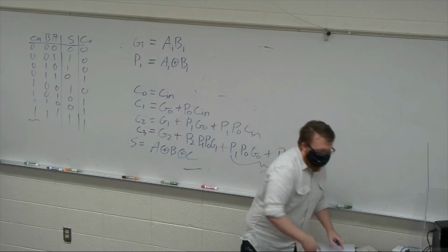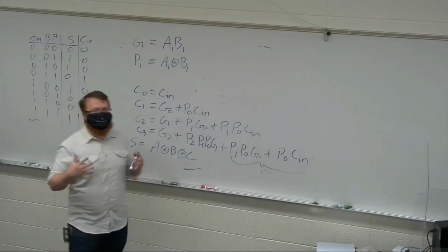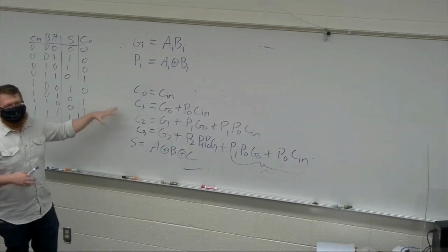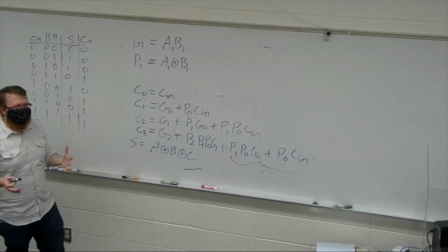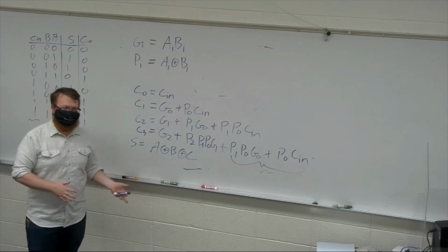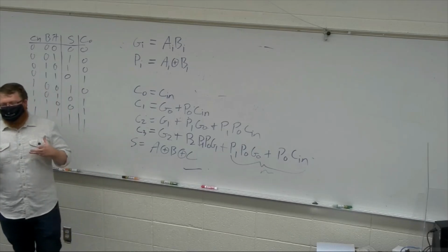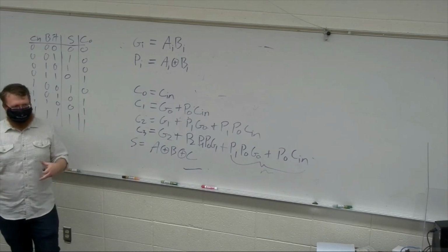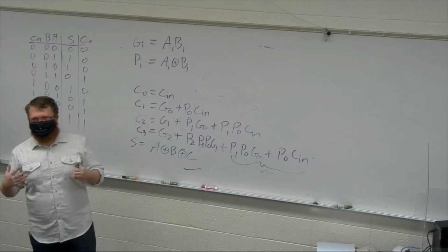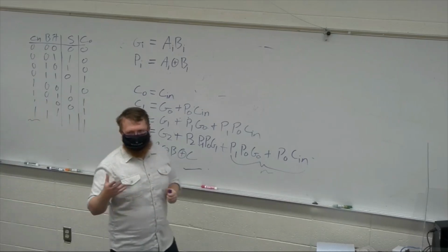Yeah. So what will happen in reality for most of you? If you end up designing something in an FPGA, you're not going to write out all of this. This is mostly helpful to be aware of how they're implemented. What you're really going to do is use what's called an IP core, which I will introduce in the current lab we're working on after I upload part 2. These are tools in Vivado, Quartus, or Lattice, which provide you nice, easy mathematical blocks. And these are going to be mapped to the FPGA, what we call fabric, right?